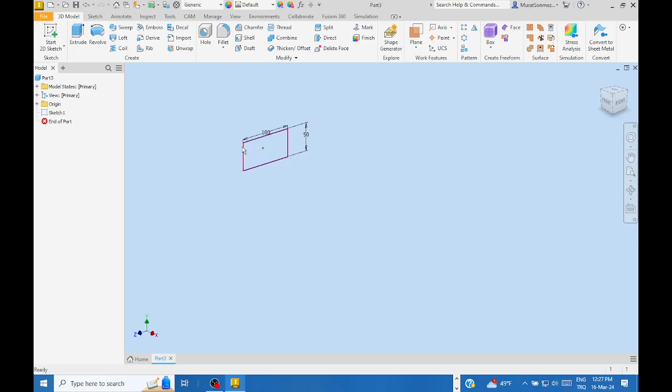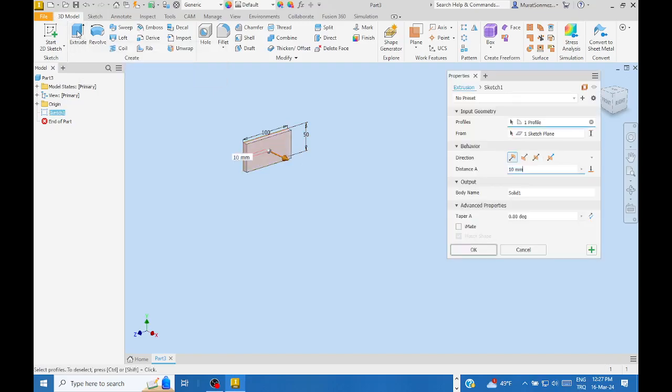And then, yes, apply the process. For a right prism, to create this model, the process is extrusion. In the Create panel, find the Extrusion button. Start the process, and then the region has been automatically detected by the software. And then into this box or that box, write the length of the prism: extrusion length 1500.